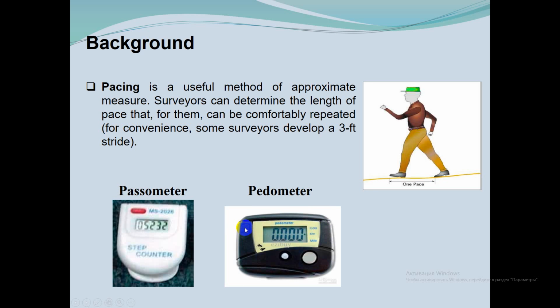Another important use of pacing is for a rough check of all key points in construction layout. Distances typically can be paced with an accuracy ratio of 1 divided by 100. So a ratio of 1 to 100.